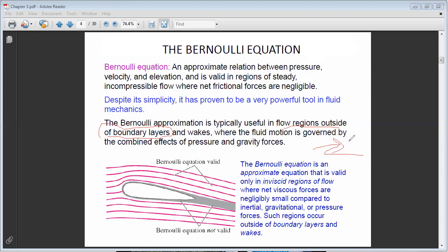The boundary layer is a region where you have transition, because your flow, let's say far from the surface, is uniform. However, if you have a fixed surface, for example, you are forcing the flow to have zero velocity there. So you'll have a certain region of transition where viscous effect will be dominant, that will give you a certain velocity profile to go from zero to the uniform profile. So this region is called boundary layer. So if you want to apply Bernoulli equation, you should make sure that you are far away from boundary layers.